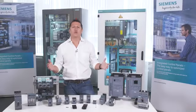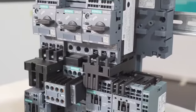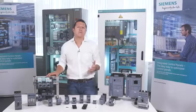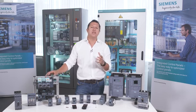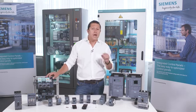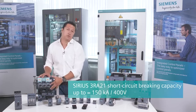Let me show you how this works. These load feeders, as a combination of motor starter protector and contactor, have been tested for a high short-circuit capacity based on IEC standards and have been provided with technical values, for example, for 3RA21 with 150 kiloamps at 400 volts.